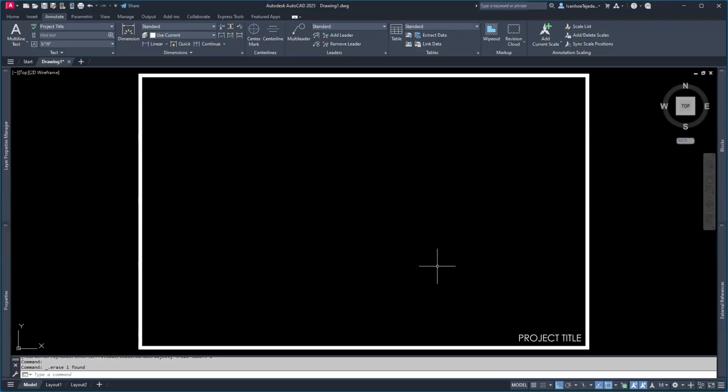All right, I realized that I forgot to show you dtext, and I want to do that. So this is MText, and MText is very common now in AutoCAD. But before we had the MText, multi-line text, we only had dtext. So let me show that to you. So for dtext, I simply type DT, and that used to stand for dynamic text, but that was way back when. Now it's just simply text, and it is single line text.